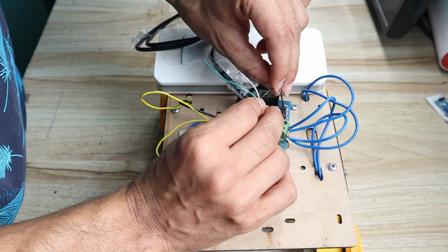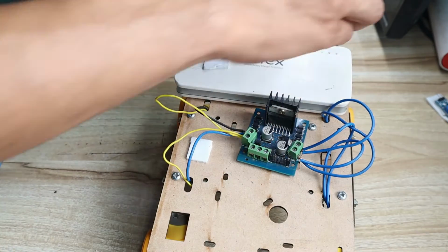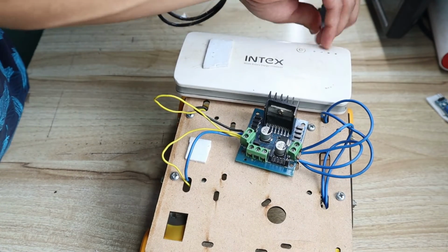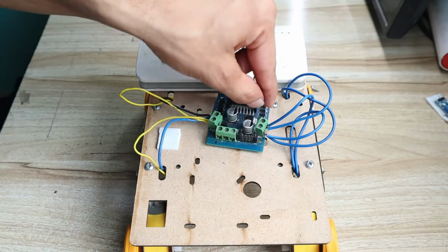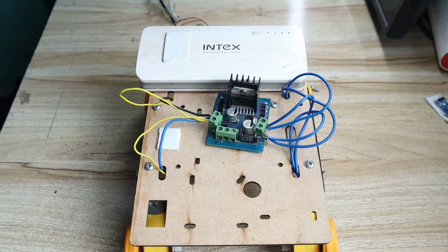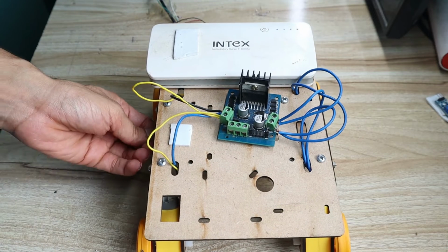that side motor. Okay, yeah, perfect. So it is rotating clockwise. If your motor is rotating anti-clockwise, just swap these two pins. Okay, the 4 motors should be rotated in the same direction. Now this is a very important step you have to do.